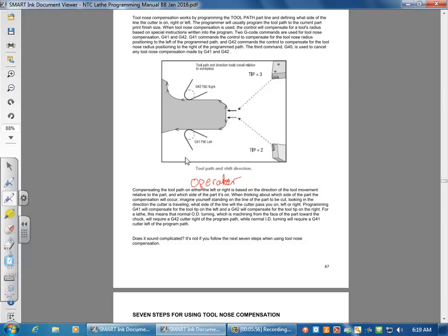Okay, that's an O. This is the operator side. So in the case of a manual lathe, your tool is coming from this side. But on the CNC or most of your slant beds, your tool's coming in from the back side. So that's in our case with our Haas ST10s and ST20s. So that tool's coming down, it's coming over and it's cutting away from you.